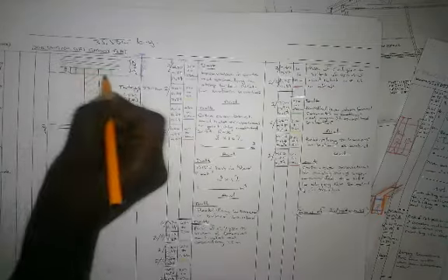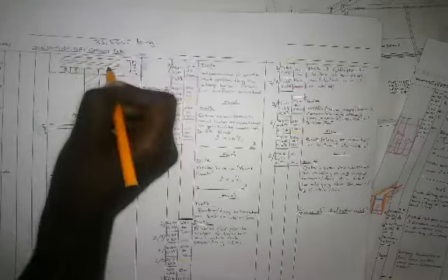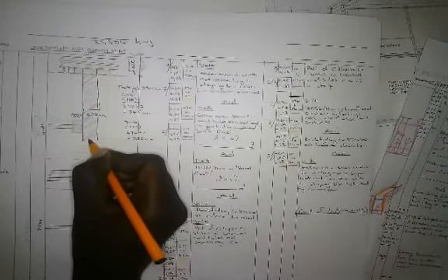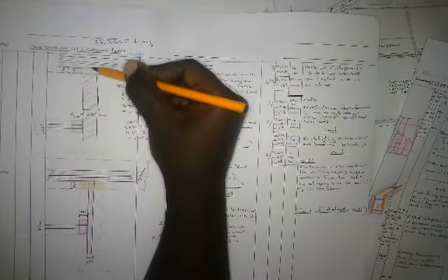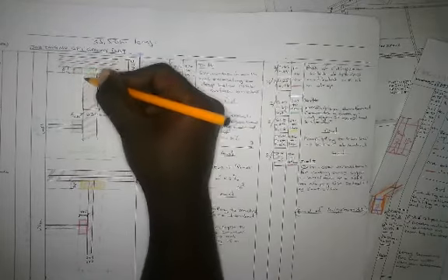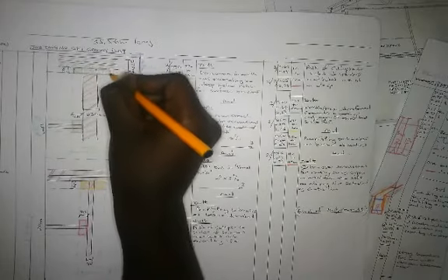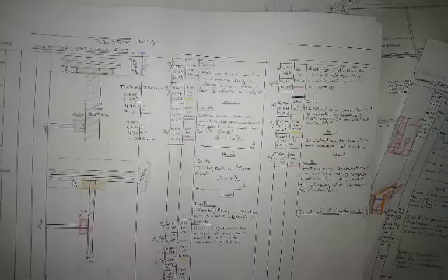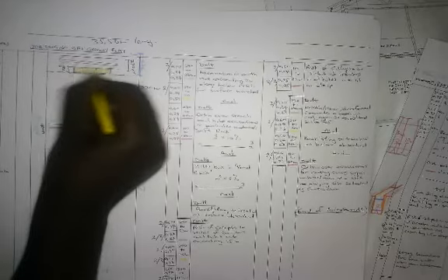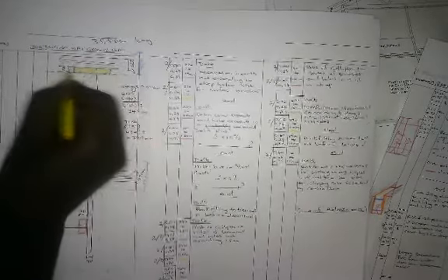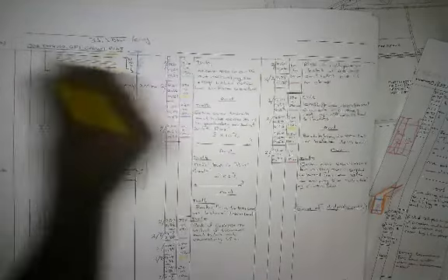Okay, that's the center line for it. Now this wall has a wall butting against it that is connected to it, which is your 230 wall. Remember there is a trench over here. That trench was for the foundation footing for your 270 wall. Now your 230 wall comes all the way across to butt against your 270 wall. So when you calculate the excavation for your 230 wall, this part where it comes closer has already been excavated.